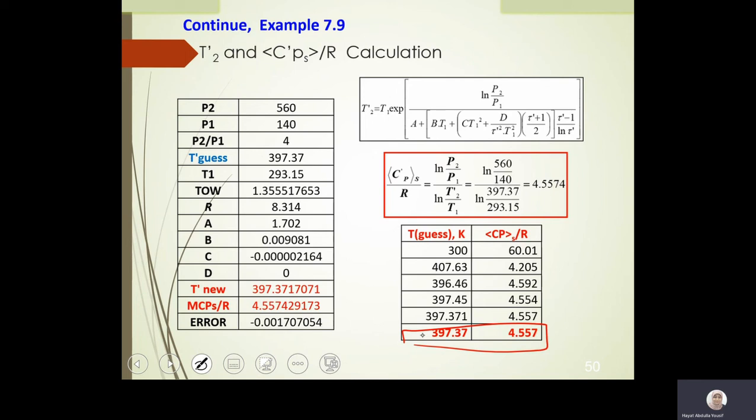Now this delta H actual, I want to substitute it here. Then why, doctora? I will tell you. In the question, they ask for the temperature difference, and this delta H is related to temperature difference through this relationship. Beta is given in the question. Pressure difference, I have it in the question. Cp is a constant value, it was given in the question. Then all I have here is delta H, which I found from the previous step. So when I substitute, I will get delta T.